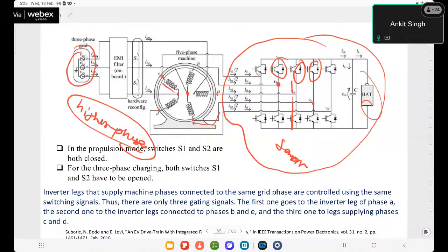Okay, so torque ripple reduction and number of phases. Another way: electric drive or electric vehicle is a specific thing where we don't want to stop the drive, because when the number of phases is increasing, its fault tolerant capability is also increasing. Fault tolerant capability means if the number of phases is reduced, our drive can still run.